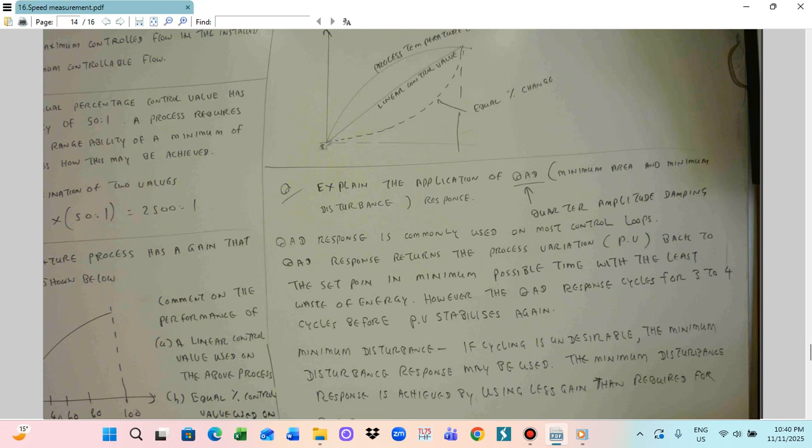So this is by using the equal percentage change, and the equal percentage change also depresses the change of the temperature. This is just the operation of the two valves. When the temperature change is non-linear and you use a linear valve, the adjustment cannot follow the change of the temperature at some intermediate points. But if you use the equal percentage change valve, it can even push down the temperature. So this is the performance of the two valve characteristics in the real process.